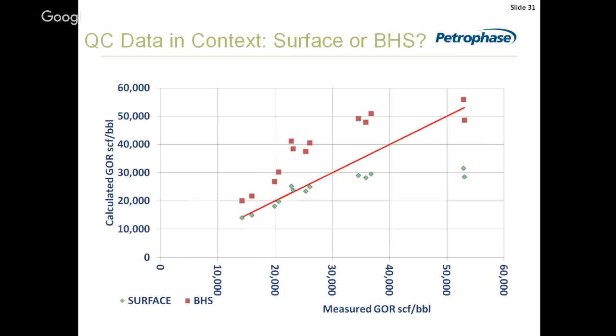So our separator condensate, we can believe it because we make our little equation of state model of that, and we can use it and we can predict it. And we know it operates over quite a range of flows. But what about above 30,000? It plateaus off. What is that telling us? Well, if you remember the phase diagram plot, what we're doing is we're actually falling into the two-phase region. Our pressure around the wellbore has fallen below the dew point. We are depositing condensate in the reservoir, so what we are producing to surface is much leaner.